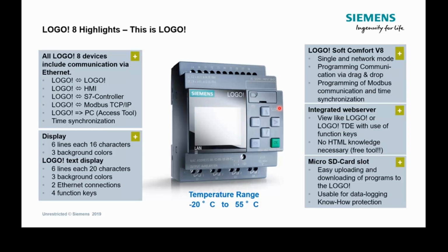So if you have a customer at site maybe, and you need to make a program modification, but you can't get access, so something that could potentially happen in these times, you can download the program onto a logo locally in your office with an SD card fitted, tick the box to say send it to the SD card when you're in the download window, and then put the SD card in the post, and the customer can then load the program directly off the card into the logo through the menu. So maybe a bit of a get out of jail free card there for you.